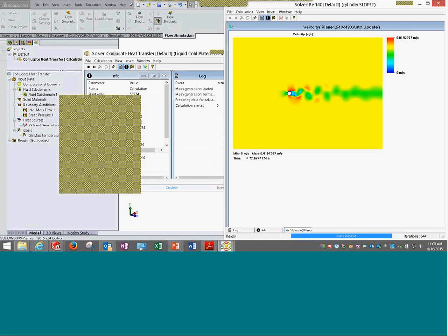Okay. Is there a way that the software can stop calculating in transient analysis when it reaches the steady state and let us know the time required to achieve steady state without setting any particular goal? No, a goal would be a must. So we can tell in the goal when to stop.